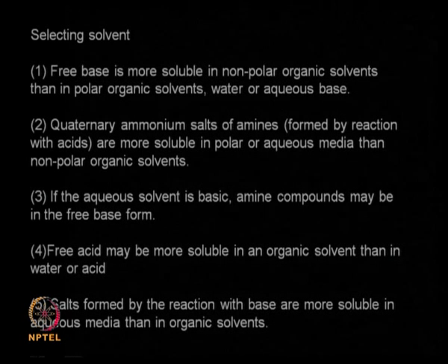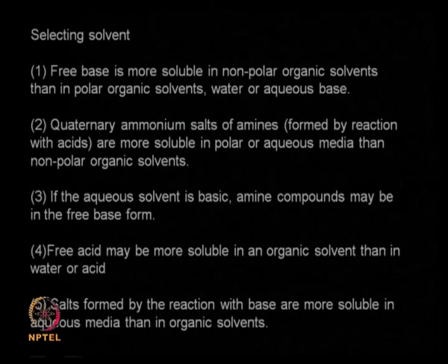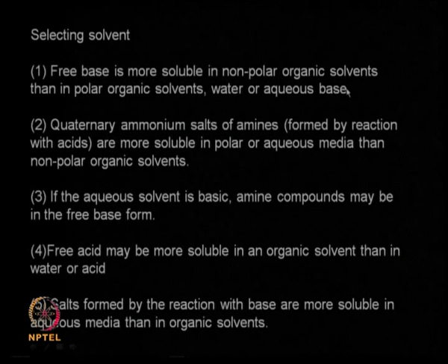So selecting solvent plays a very important role and it depends on the type of product which you are trying to recover. Number one, it depends on the pH conditions of your fermentation broth, and it depends on whether it is aqueous or a non-aqueous situation. For example, free base is more soluble in non-polar organic solvents than in polar organic solvents, okay, like water or aqueous base. So you need to keep that in mind.